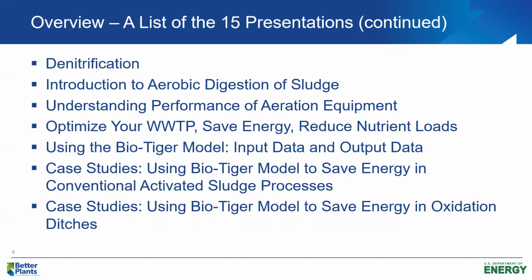We'll get into aerobic digestion of sludge, and although that's not activated sludge per se, when we design and operate an activated sludge process, we're going to produce waste sludge, and we've got to deal with it. One of the ways that we stabilize the sludge is through aerobic digestion, and sometimes aerobic digestion can be a big energy consumer because it takes oxygen to stabilize the sludge aerobically. So we'll get into that.